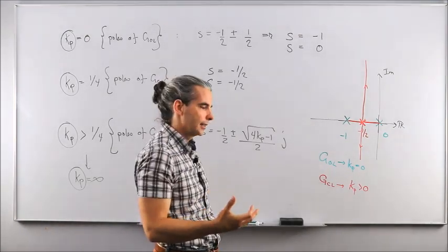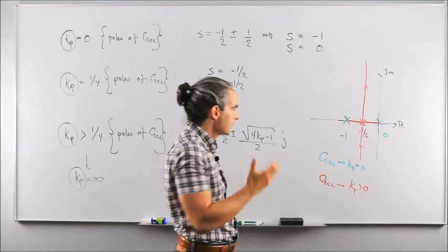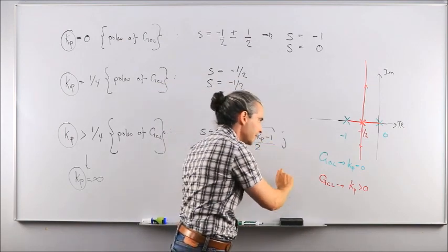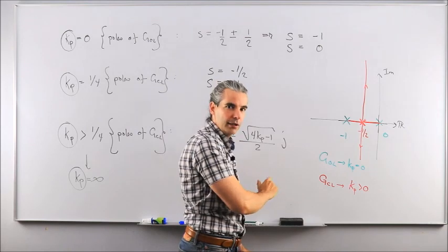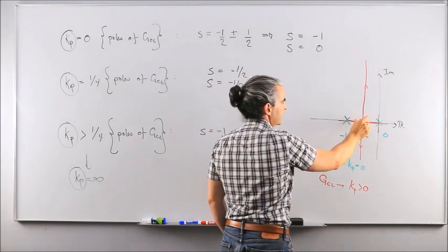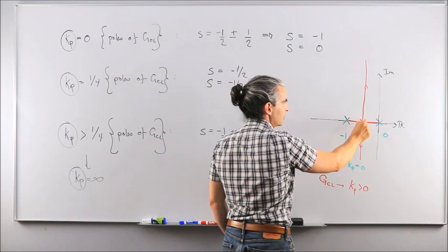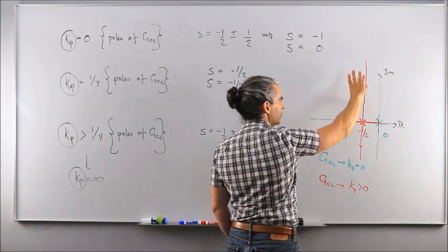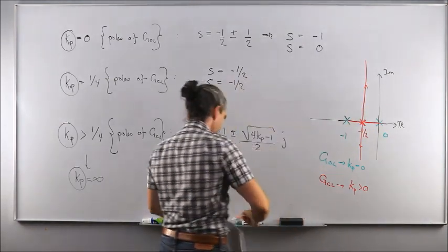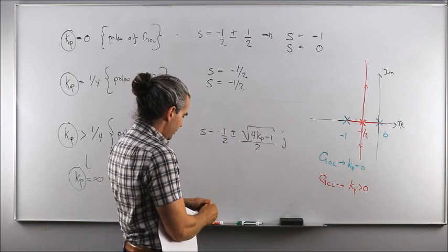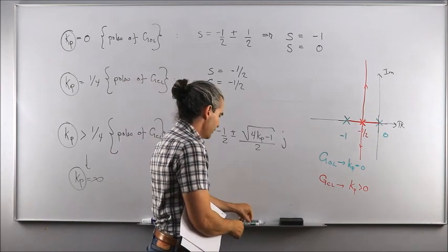So that tells you that if you have this block scheme diagram of a modified PD controller acting on a single axis spacecraft rotational motion, as you increase Kp, or as you crank Kp from 0 to infinity, that would shift the transient response of the closed loop system, because the poles will be moving, okay?